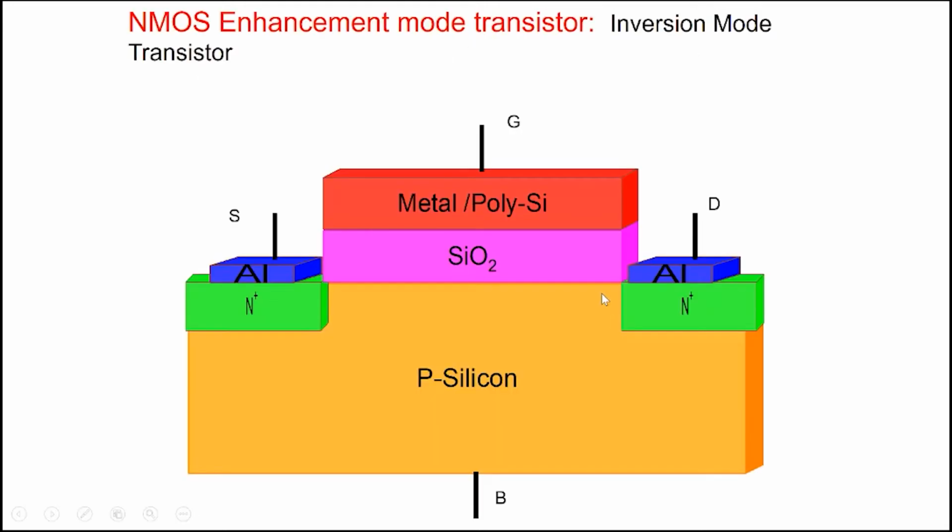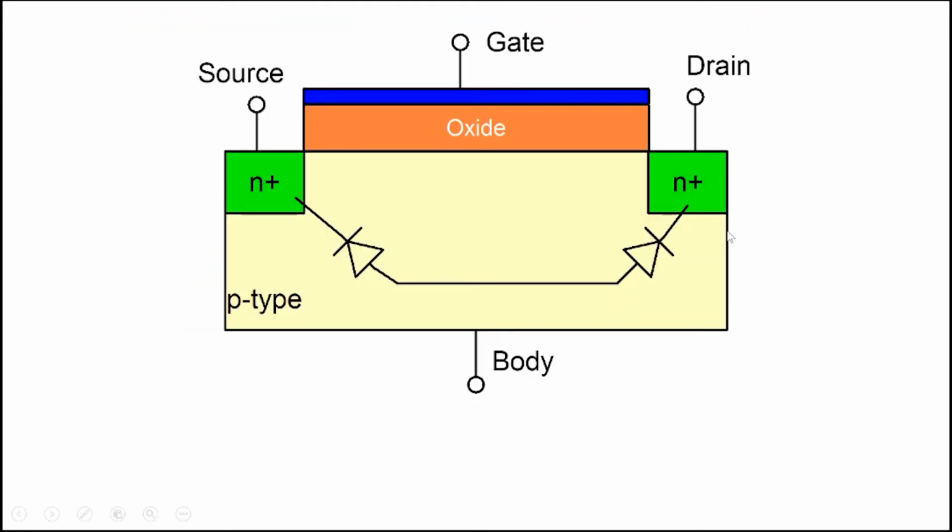So this is a simplified schematic of our transistor, MOSFET here. So again, there is a gate, metal here, oxide here, P-type semiconductor here, N+ region source, N+ region here drain. In this case, the source and the drain can be interchanged. So it's a symmetrical device. And note that because the body is P-type here, there's effectively a PN junction here. N plus P is a PN junction. And there's another PN junction here at this particular point.